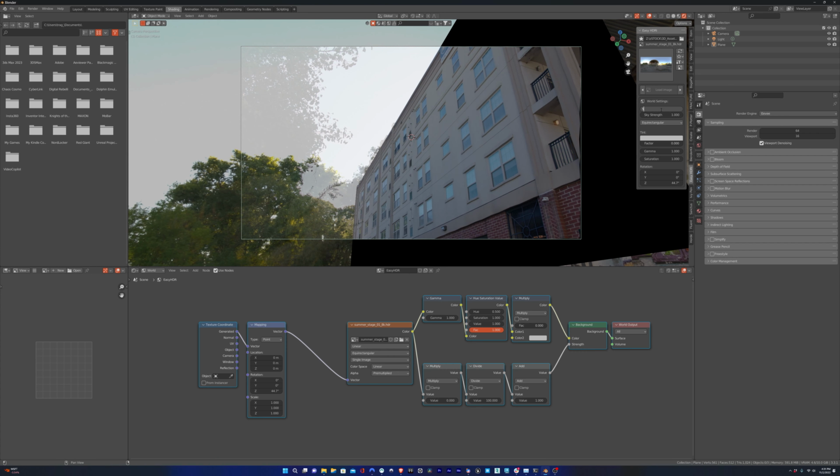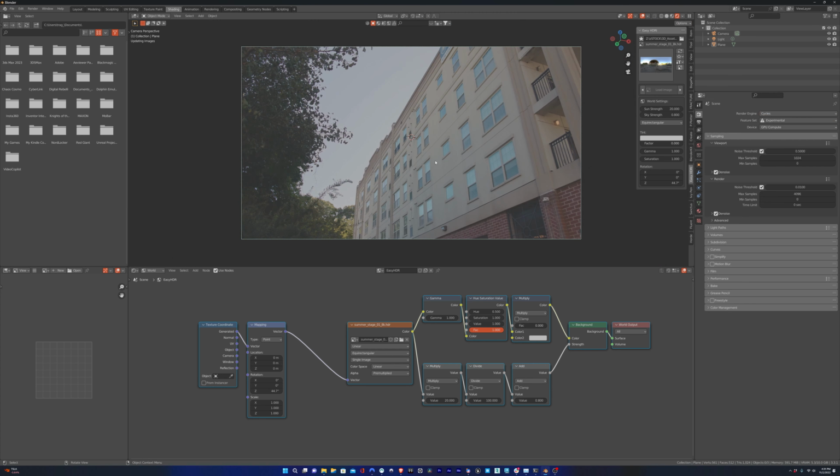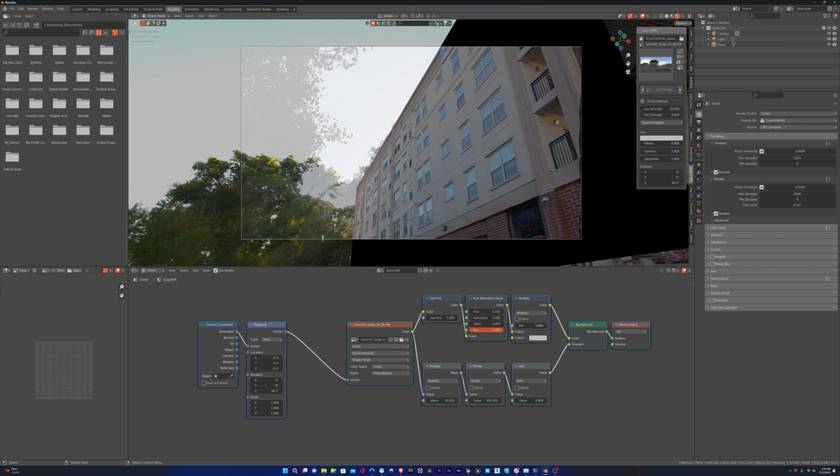And that's pretty good. I'm going to bring the sun strength slightly up because I don't want it to be too blue, but then the sky strength I'll bring to 0.8, and then actually we'll just do like 20 for the sun strength. I'm going to switch back over to Cycles so that we get a better view of what we're doing, because that's how we're going to render it anyway. One of the things that I'm seeing here is that we're getting this overlap, and it's two images. It's basically the background image and the HDRI.